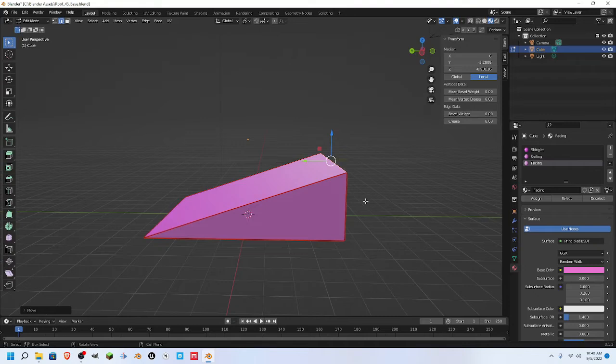The reason we went 9 on the y-axis, I didn't explain this, is so that we have a 1-foot overlap over our walls. That's actually going to give us about 9 inches because the walls are about 3 inches deep. So that'll be about a 9-inch overlap, and it'll give us just a little bit of eave and make it look like it's supposed to be there.